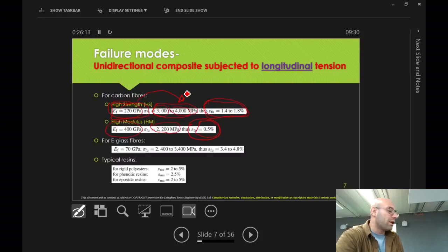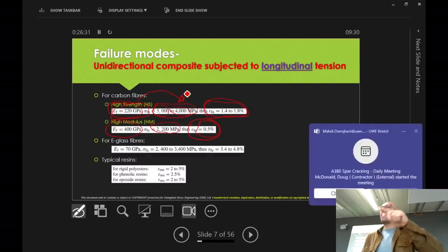Let me give you an example. If you have a heavy structure, you don't want it to buckle. In many of the aircraft aerostructures, not on the spar, on the spar we do allow buckling and post-buckling, but on the skin of a wing, we don't allow any buckling, because if that buckles, your aerodynamic surface would be compromised. So for buckling, you want a very stiff structure that resists buckling. But if you've got post-buckling, so you allow the structure to go beyond the buckling region, then you want something that's strong, that can go on and on and on. So it's really dependent on the application.